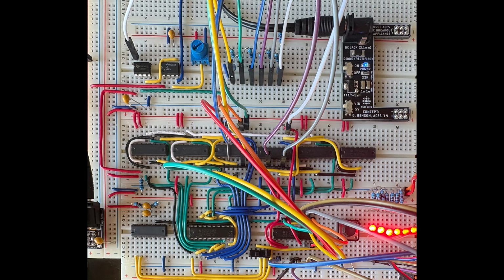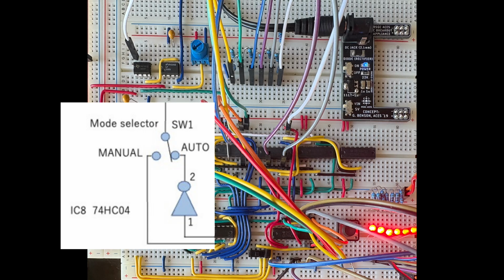The circuit can operate in two modes, manual and free running. In manual mode, each conversion is triggered individually using the switch, allowing the process to be observed step by step. In free running mode, the clock continuously drives the SAR logic, so the circuit continuously repeats and converts the input voltage and updates the output automatically.